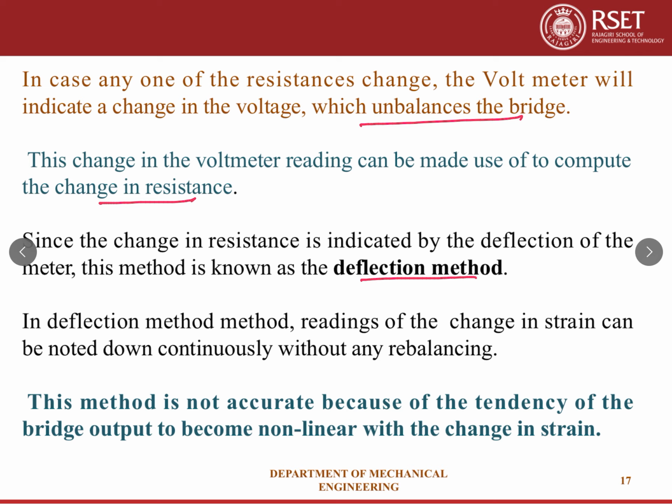So in the deflection method, the reading of the change in strain can be noted down continuously without any rebalancing. Here rebalancing is not required. And this method is not accurate because of the tendency of the bridge output to become non-linear with change in the strain.